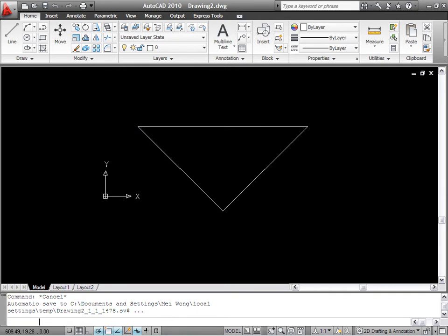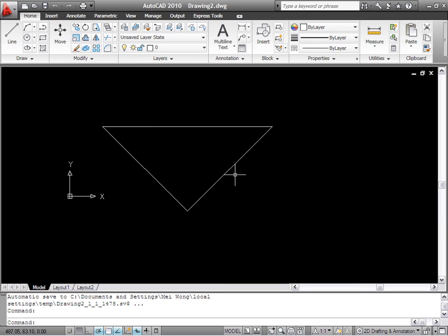So this is the first lesson on how to create lines and using the polar tracking for the angles, object snap to determine the points that I want to snap. By having object snap tracking, I can detect the points that I want and move along the tracking line.